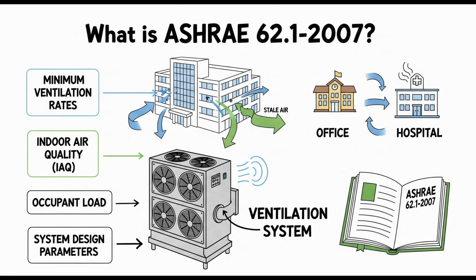You look for nearby potential contamination sources, exhaust vents from kitchens or labs, maybe garbage dumpsters, loading docks, cooling towers. You even look for visible plumes, note any weird smells, check the prevailing winds. So you're literally scouting the neighborhood to see what nasty stuff might get sucked into your fresh air intake. Pretty much. And the results from both the regional check and that local survey, they have to be documented, reviewed. If the outdoor air looks particularly bad, it might mean you need extra filtration or treatment steps inside the building system.